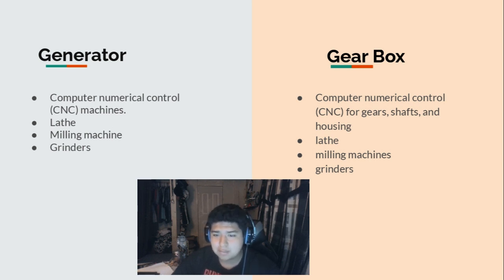And for the gearbox, I would also be using a CNC machine, computer numerical control, specifically for the gears, the shaft, and the housing. I would also be using a lathe to make sure that I can get those fine precision cuts in there, as well as a milling machine and a grinder.